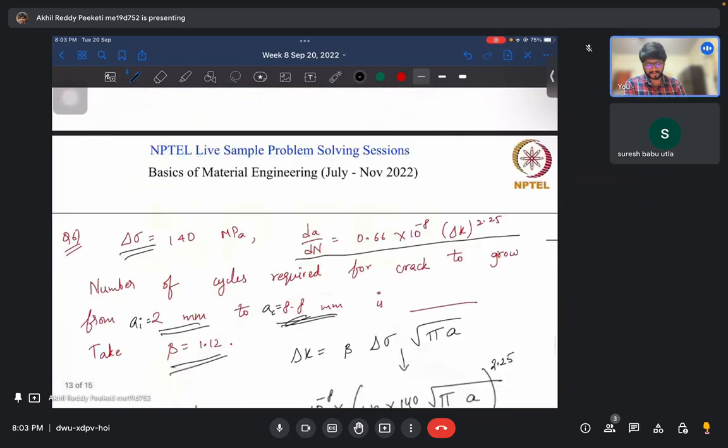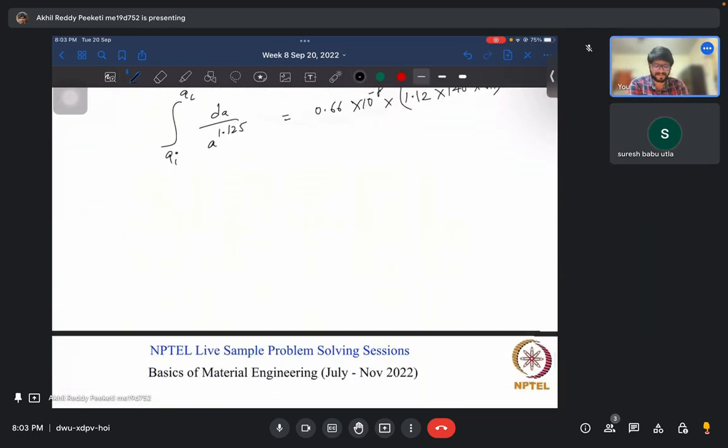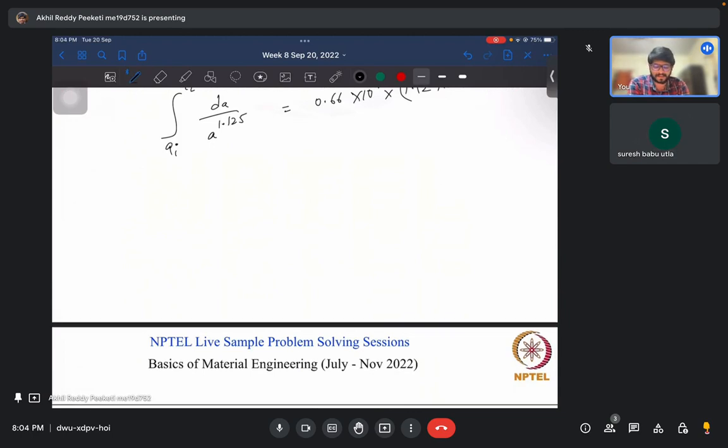If I tell that, I am actually telling the answer, so I don't want to give this. Those theory based questions, you can think of it this way. Whenever it is fatigue or stress concentration factors, that question. If you are talking about axial load and torsional loading, see how the stress diagram would be. If you have axial loading, the entire part will have the same stress, right? The entire shaft. But when you have torsion or bending, only the outer diameter will have the highest stress. Based on that, you can answer that question.